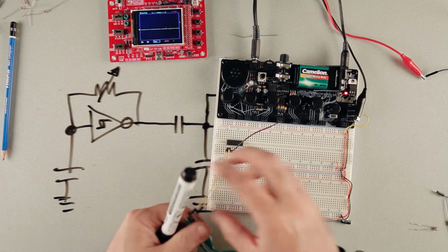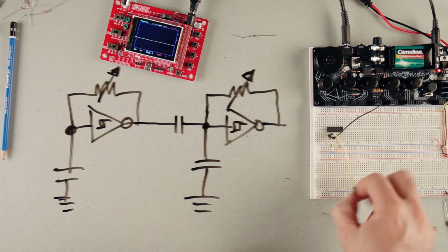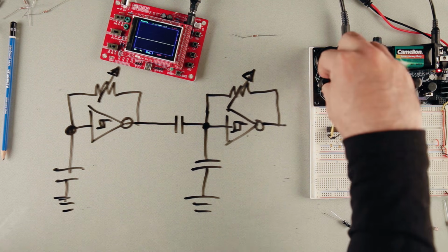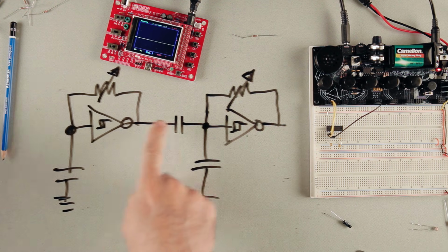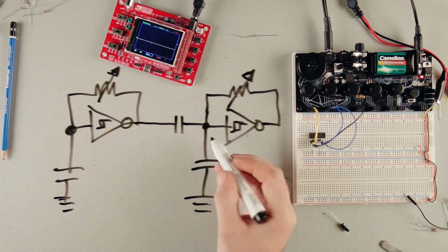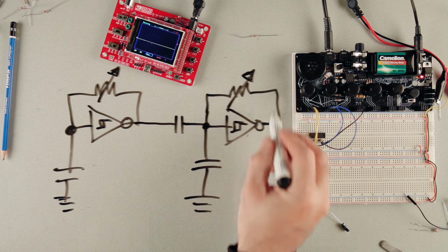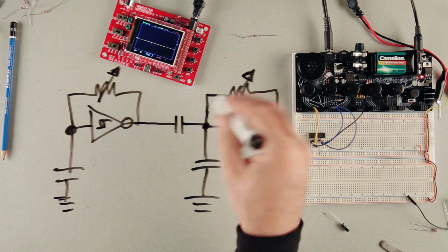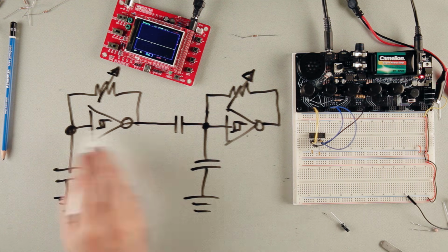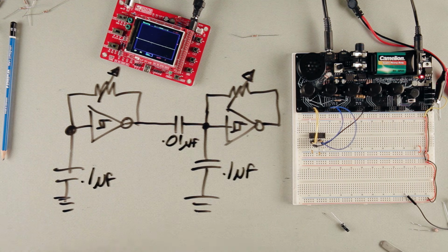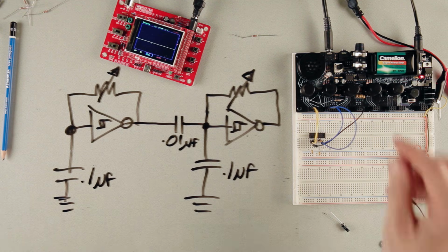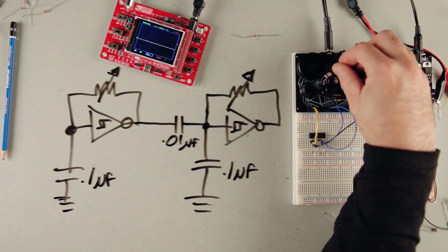Okay, and let's plug these to potentiometers. And what's happening is I'm feeding one of these oscillators into the other one through a capacitor. So as the current is going back and forth and it's doing that bounce back and forth that makes our oscillator, we're also getting a little bit of signal from this one. It is syncing this oscillator to that one. And rather than trying to explain it, I'll just play it for you and you'll see what I mean.